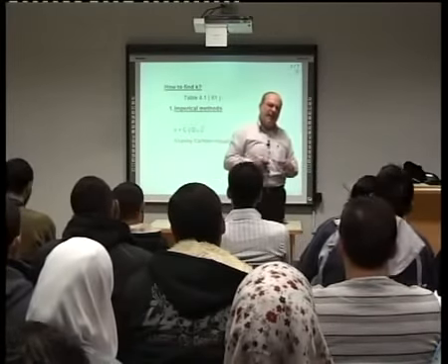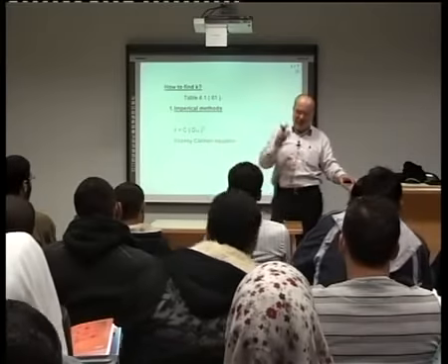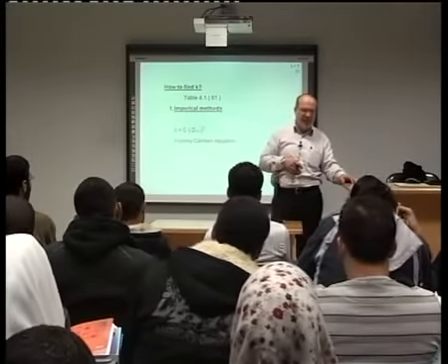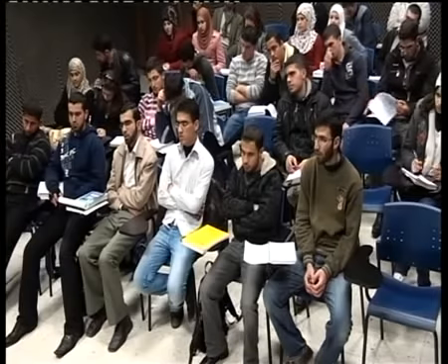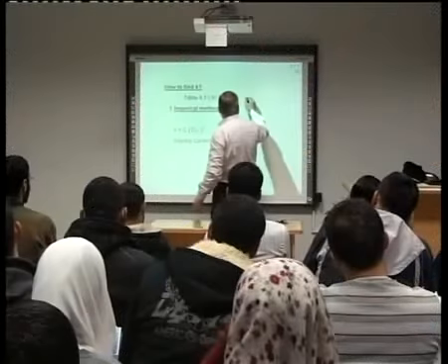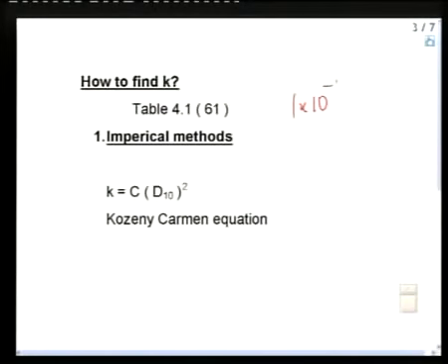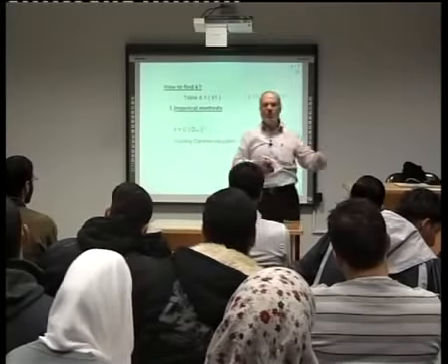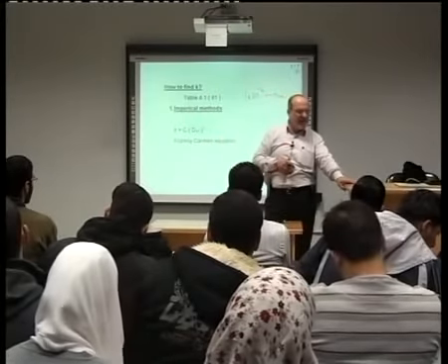But if I have clay, especially if I have bentonite, remember that troublemaker? Okay, bentonite. It may reach 0.00001 centimeter per second or even per minute. You see how much is small? Even it may reach 1 times 10 to the power -7. Okay? So that explains why I always have problems with clay if I have water, not with sand.